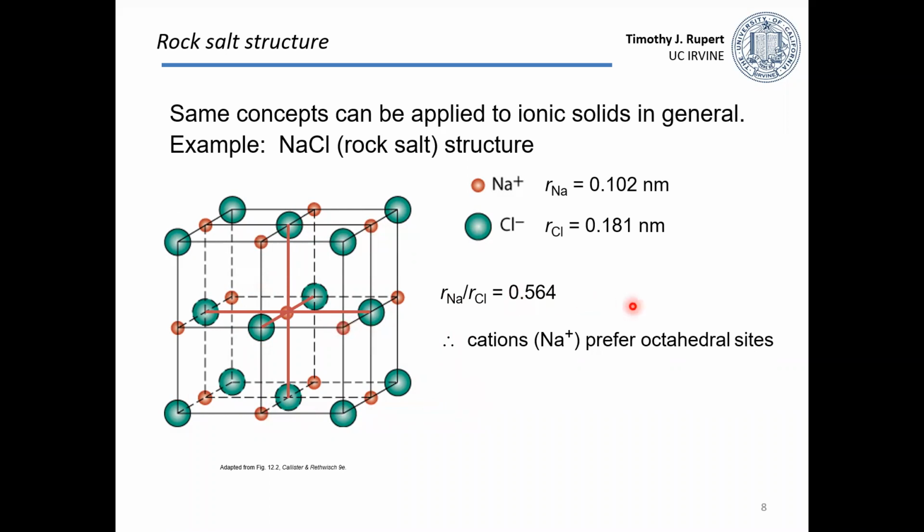All right, but getting back to the relative size, we can look up what the ionic radii are and take that ratio, and this is going to be 0.564. That would be from our table where we read that we would want octahedral sites, and sure enough, that's the type of site they form. So this has 4 ions in the plane, 1 above and 1 below.